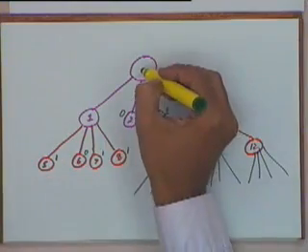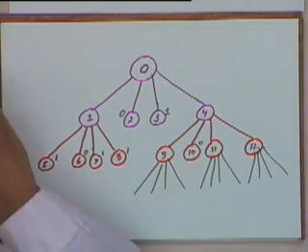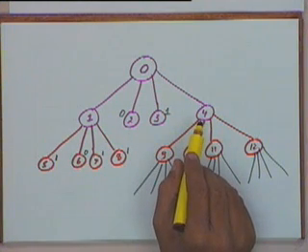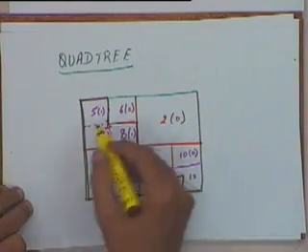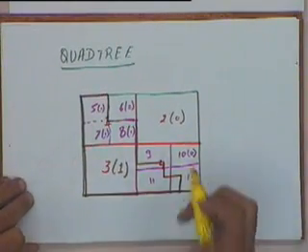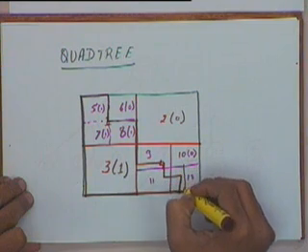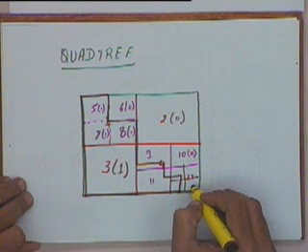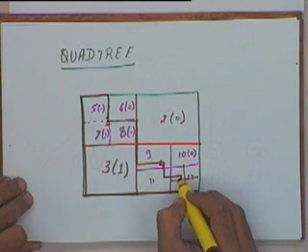So at every node, let's say this is my node number 0, at every node we are dividing a space into 4 parts, and each part we are trying to say whether it is inside or outside. This way we can continue till the whole of a solid or the whole of an area has been marked with 0s and 1s, or till, let's say, if I divide this 12 further, now this portion is totally outside, this is also totally outside, but this portion is again partly outside and partly inside, but now I might decide that this is too small a portion to be considered.